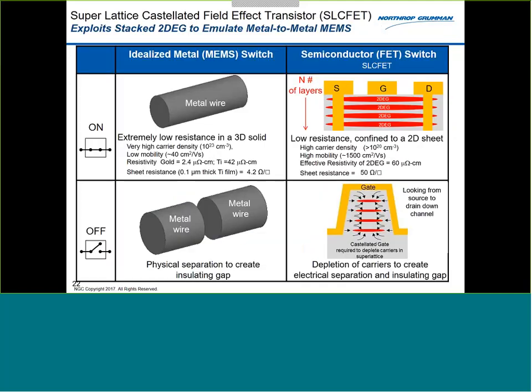So he asks, what type of dielectric do we use between the gate and the material? We're working in an alloy GaN system, and for us we find that silicon nitride is most effective. That's not the only one that could be used. Using a MISFET type of structure is important for this because we need to make sure that we don't have any conduction between the gate and those channels.